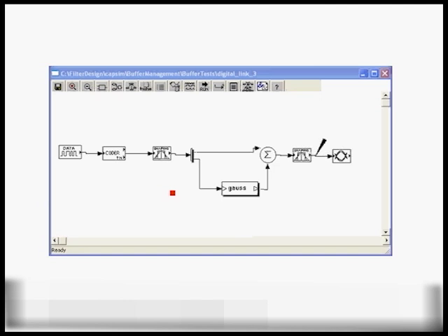no blocks have any more activity on their input or output buffers. In that case, the source block is revisited, a chunk of data is generated, and the simulation continues until the source block runs out of data to generate, or there is a complete deadlock in which there is absolutely no more activity on either input or output buffers within all the blocks within a hierarchical block, and so forth. Later on, we'll have more discussions on the actual details of the simulation modeling and how the kernel arranges and schedules blocks for execution.